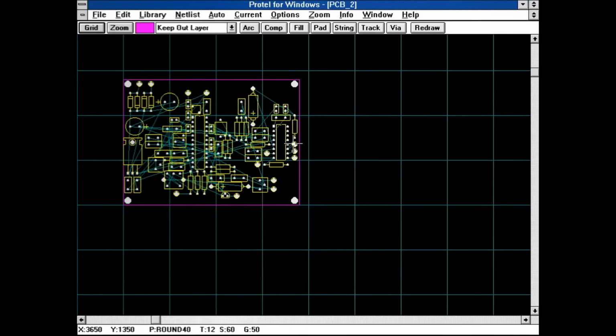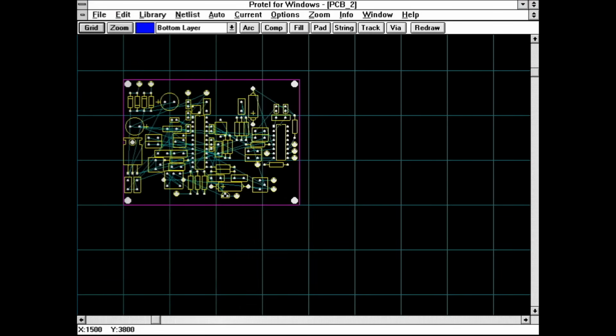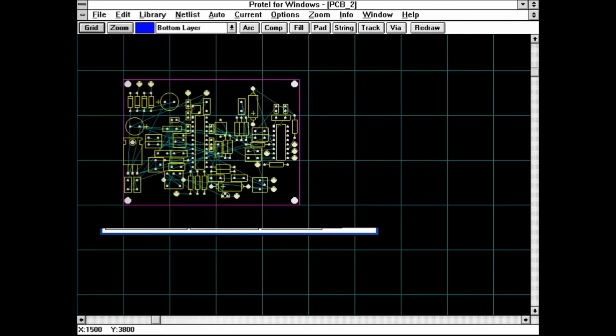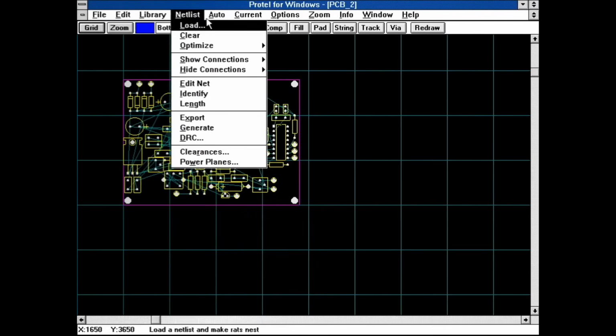About an hour later, I had all the components placed. I'll be printing the pattern out on my 9-pin dot matrix printer, so I'm using a 30 thou track width to cope with the low resolution. 30 thou is about 0.75mm. So, time to start connecting everything.